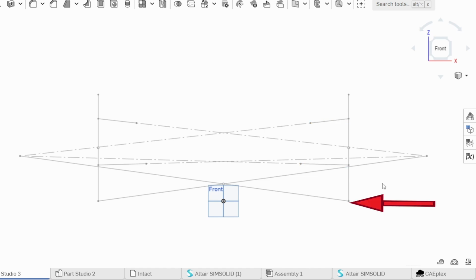For my calculations, I like to simplify it. I just take the instant center location, and I know the wheel center location, and I draw a line between the two. We'll call that the end line. So you take the lateral component of the tire force, and you'll have this known angle of the end line, so you can calculate the vertical component of the force. And I use that as a jacking force.